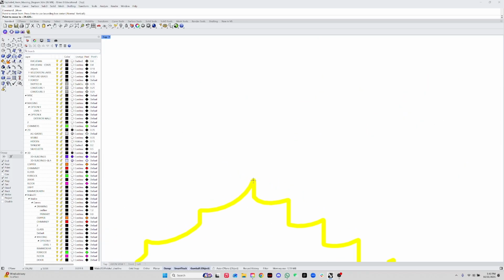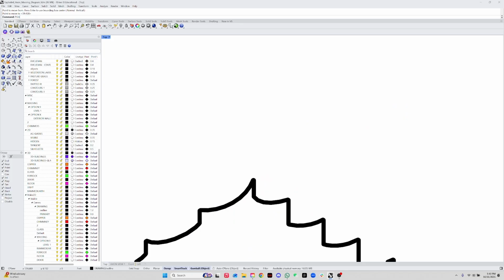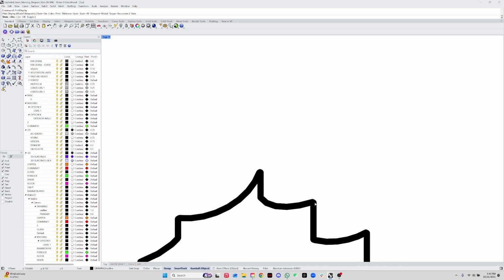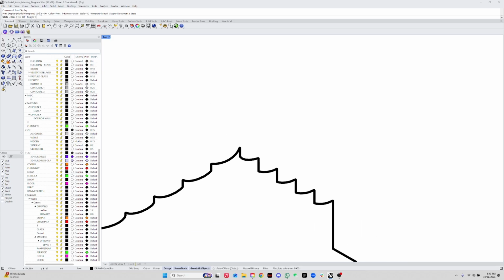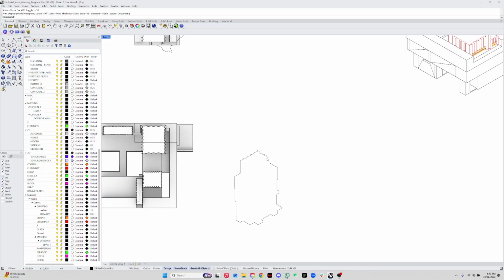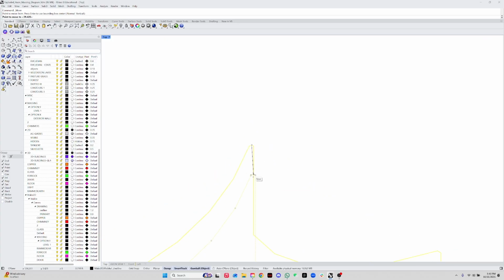So I have it right here. I'm going to take out my line weights for a second to work. One thing, if you work with line weights, sometimes you don't really get to see where the ending point is because it's thicker. I turn it off just to be a little more precise. So for now, I'm going to turn the line weight off, so then I can be a little more precise when I do this process.